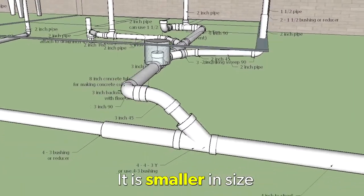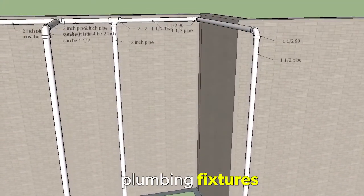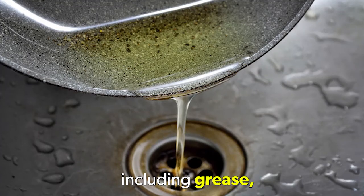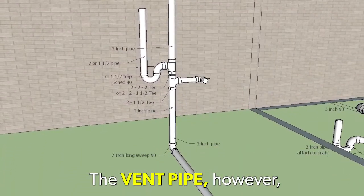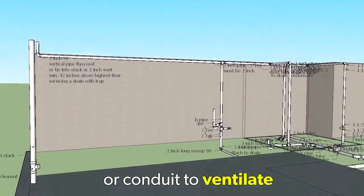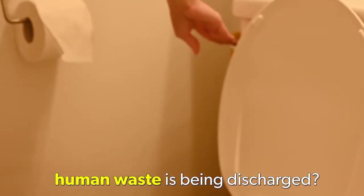It is smaller in size than the soil pipe due to the kind of waste it receives from various plumbing fixtures, suspended in water waste including grease, lint, matches, hair, garbage, and many other objectionable substances. The vent pipe, however, functions in a plumbing system as an air passage or conduit to ventilate the drainage and the waste pipe installation. Ever wondered where the solid human waste is being discharged?